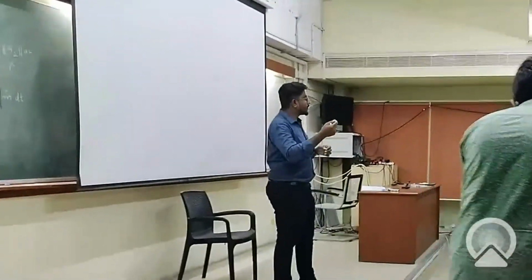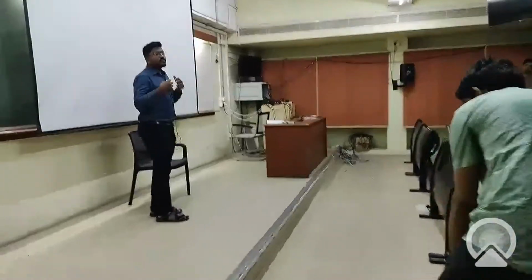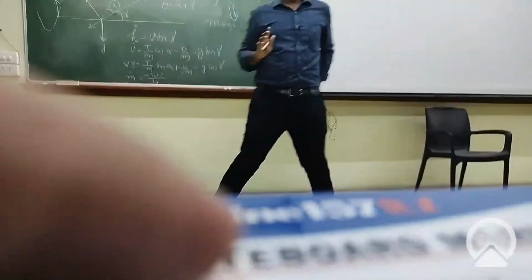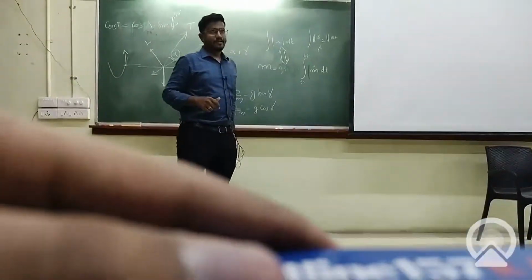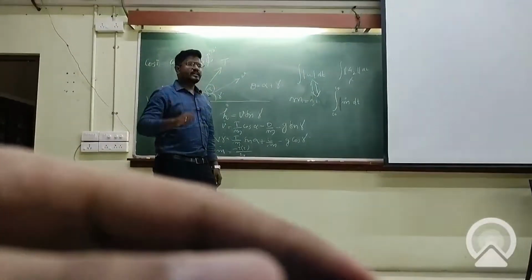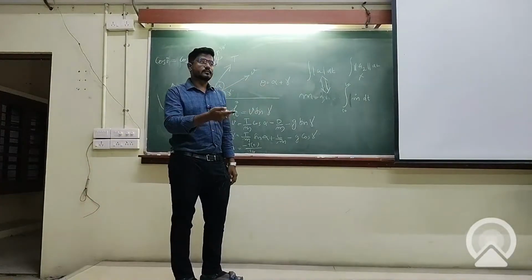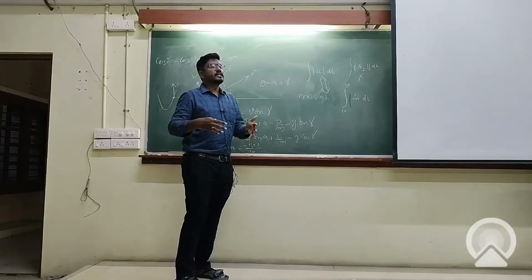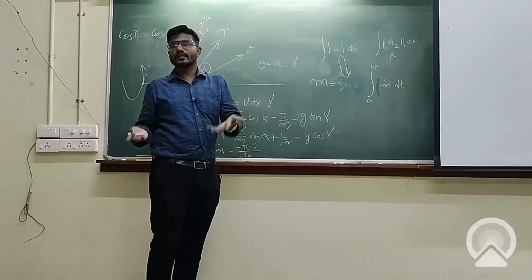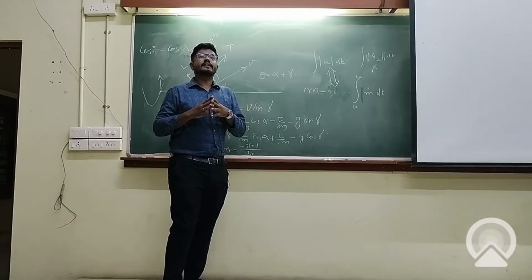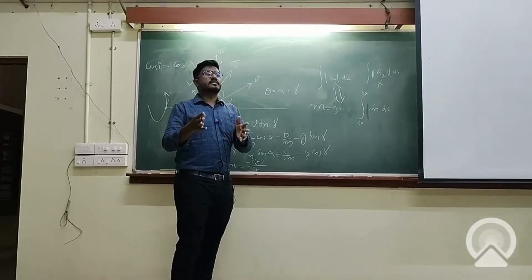This is the longitude of the ascending node. How do we achieve a longitude given longitude of ascending node? That is determined by the launch time. When do we launch? Your launch time is very critical in achieving the longitude of the ascending node. So that is why we launch at midnight, early in the morning, late in the evening. That is because all these missions have a different longitude of ascending node required.